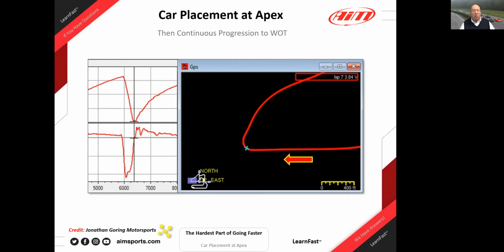So here, on the top left-hand side, we just have a speed versus distance trace. I love this trace because we can tell more about what's happening than from any other single thing. We see the acceleration up to Sebring, turn 7, which is the safety pin, the hairpin. And we see a nice uniform linear deceleration, which means we have a constant rate of slowing.